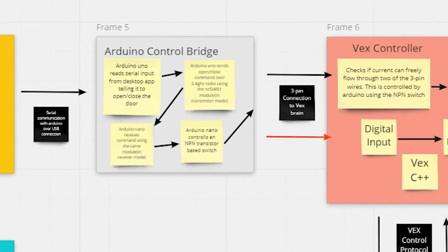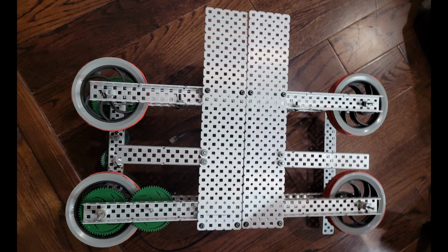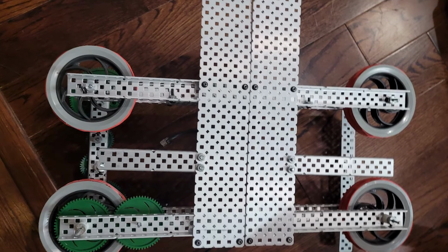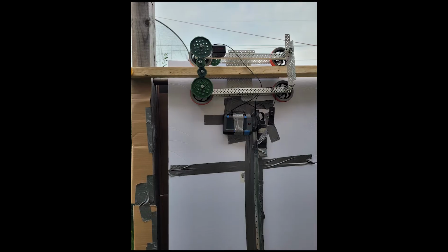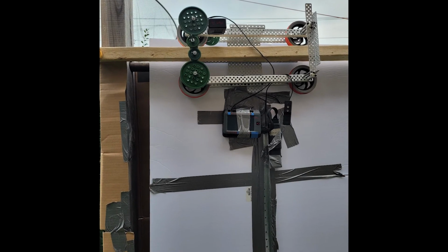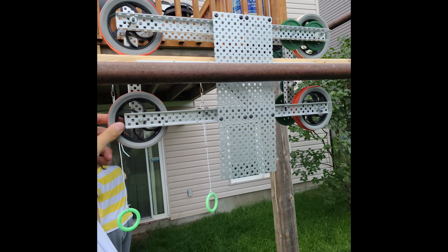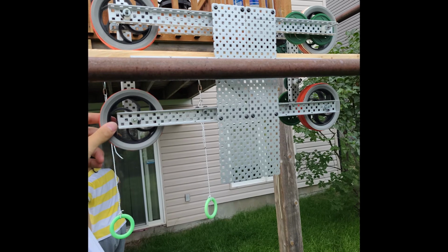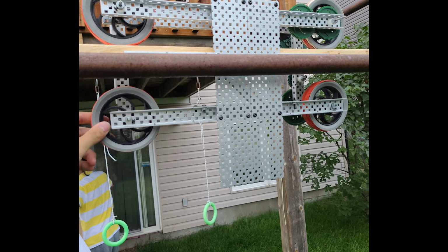Finally, let's take a look at how we made our mechanized door. The hardware portion of our project consisted of a chassis that carried 4 wheels. There were 2 pairs of wheels opposite to each other, and they essentially pinched a wood platform to avoid any slip. The driving wheels were then synchronized through a series of gears, and they served to move the door smoothly.